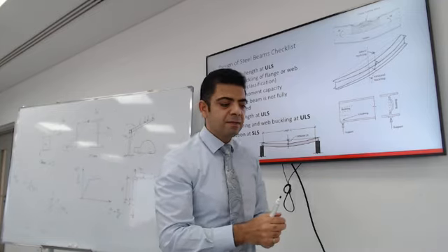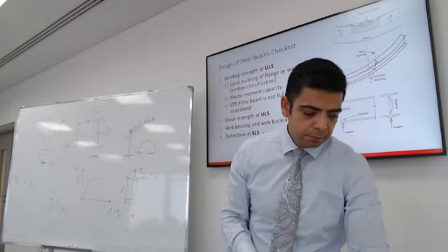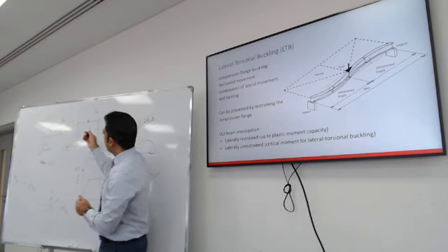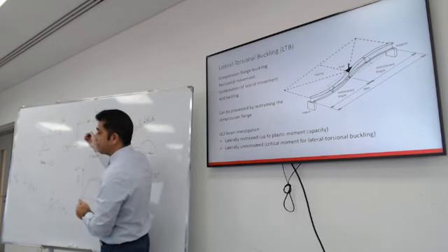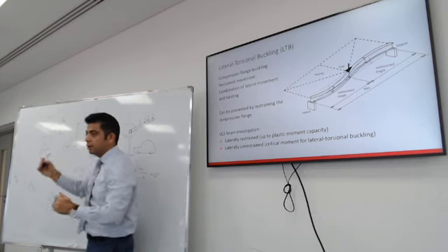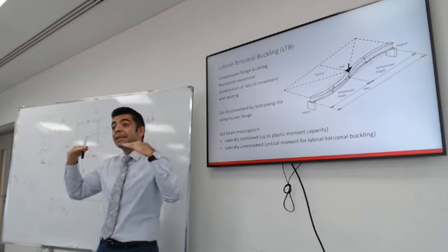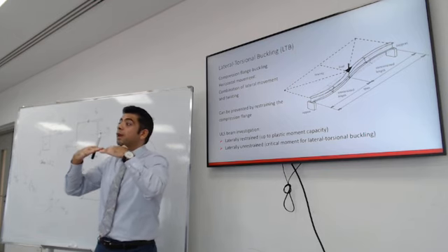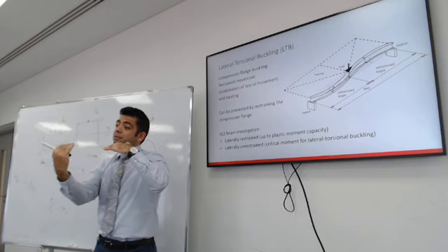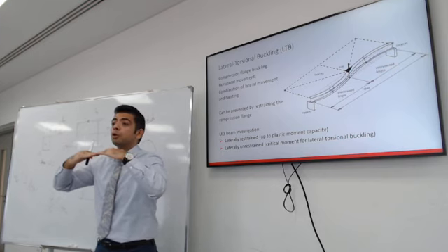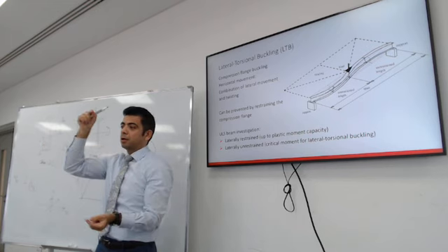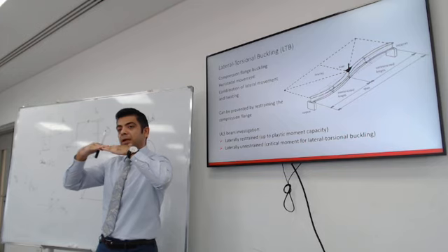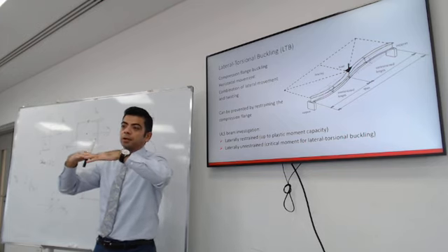So what is lateral torsion buckling? Lateral torsion buckling is because the top of the beam under gravity load is under compression. Compression is trying to get the length of the top fiber shorter. It's like trying to compress it. So if the beam is not braced from the sideways, it will go shorter sideways. It will buckle. Just like a column, it will buckle. If the top of the beam is restrained in place, it will not have this type of failure.